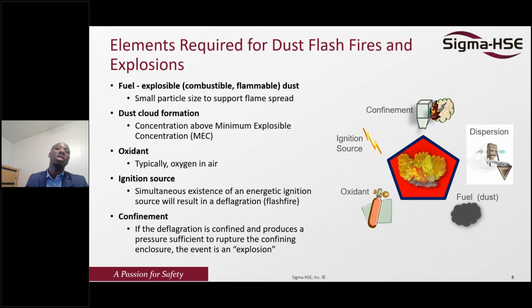Metal goes through heterogeneous combustion and organic goes through homogeneous combustion. For an organic solid, if I disperse the material, the first particle will ignite. The ignition will give off energy. The energy release will move to the next one. Then the next one will also move to the next one.